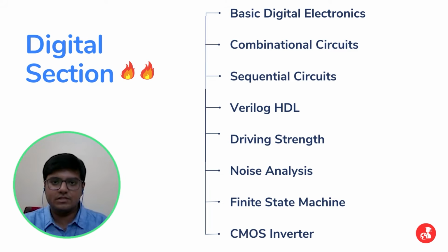Next, there were also questions from Verilog HDL. There were one to two questions from Verilog HDL. They were basic questions; one can answer easily if the basics are clear. Now there were also questions from the concept of driving strength. By driving strength, I mean the sizing of the MOSFET, how we can increase the output or increase or decrease the output time constant by varying the width of the MOSFET. Such kind of questions were also there.